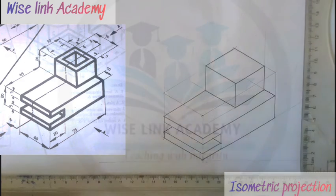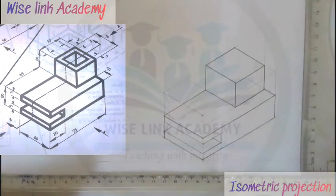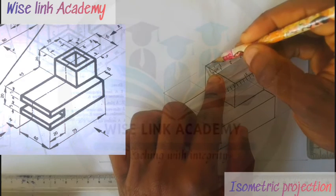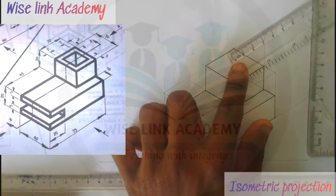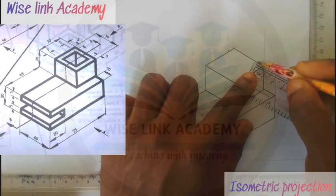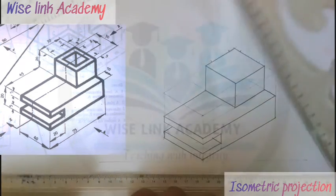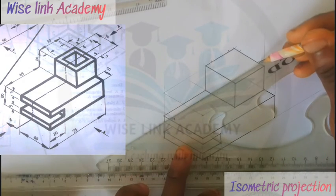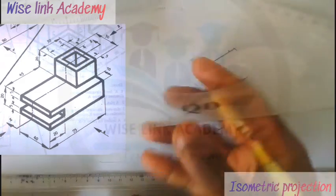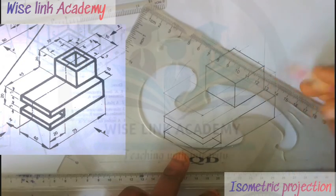We still have an inner box here, right? To establish the inner box, I will measure 5 here. Observe 5 here. Come to this point here too, 5, right? So I'll take my T square in this sense. I'll draw a faint line. Come here, I'll draw a faint line. Similarly, I'll come down here, a faint line, and also a faint line. Observe the kind of box it produces.